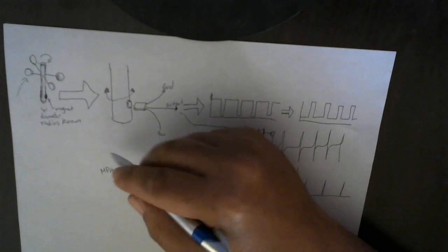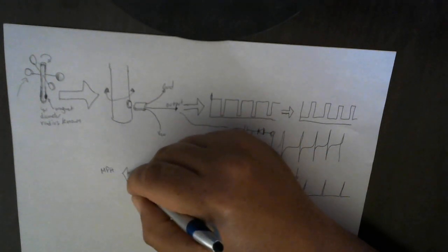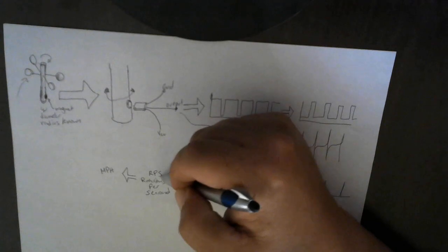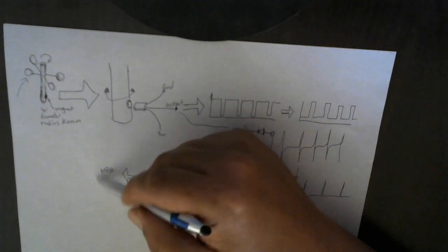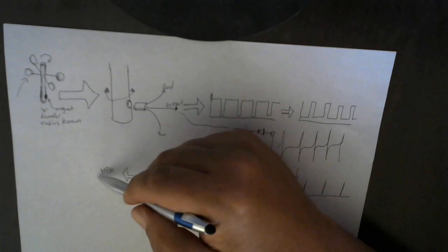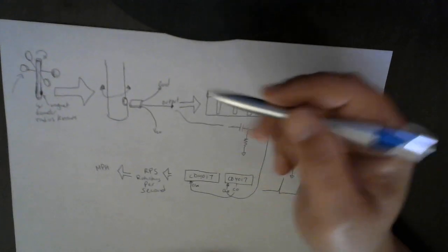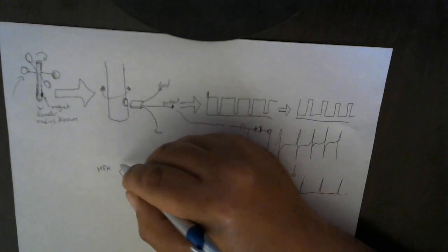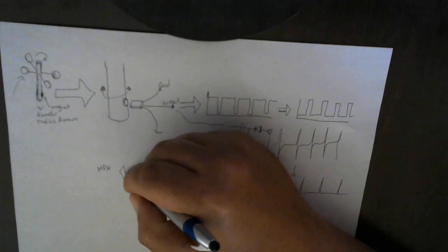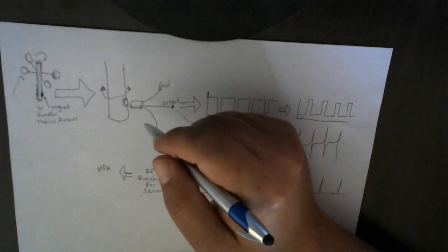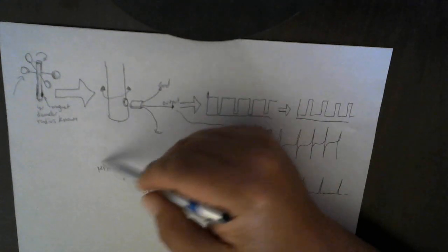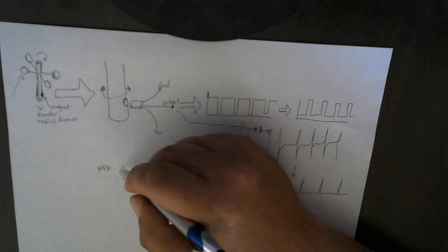So simplest way of doing that is basically math. If you had a microcontroller, this value goes into a microcontroller, you do some code, and you do the math in the code, and that spits out a value in the output. But I want to do this without a microcontroller. I want to do this all analog. So microcontrollers don't work well out in the ocean, near the ocean. The salt in the air will corrode them very quickly. So we need an analog type of circuit that's going to do this.